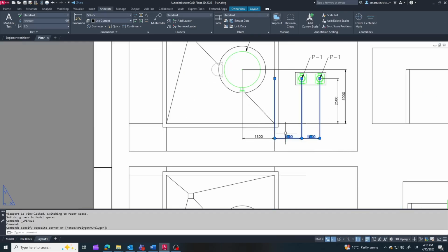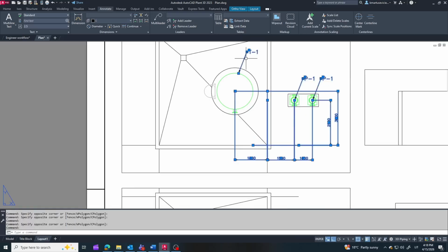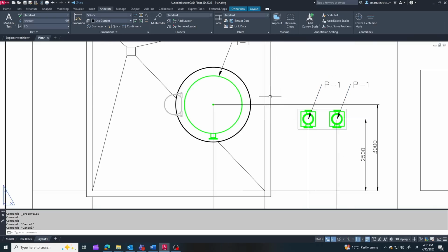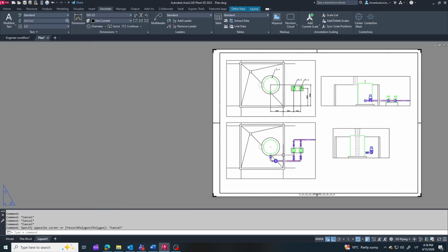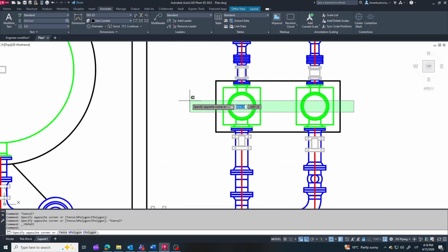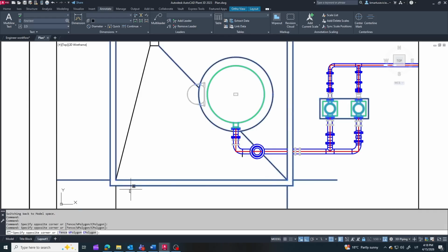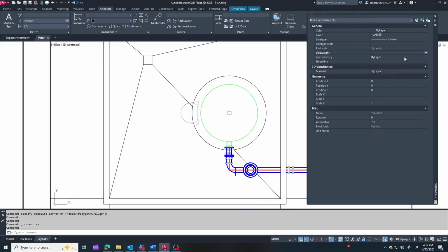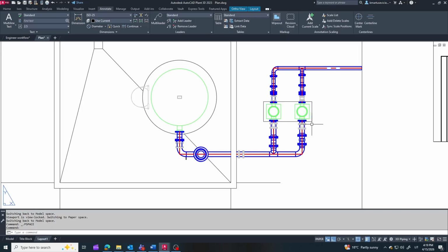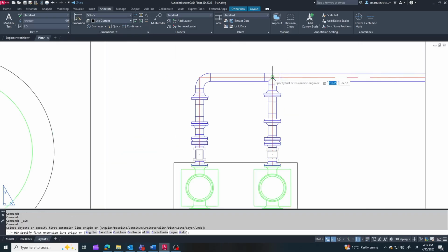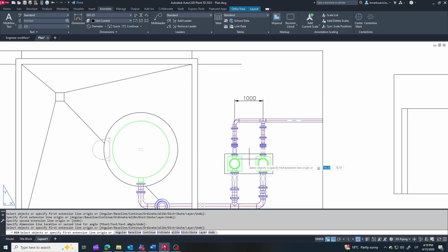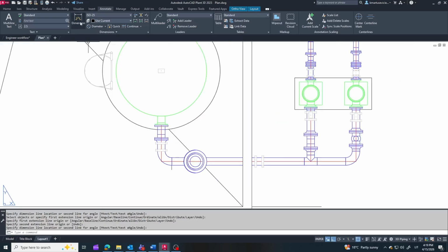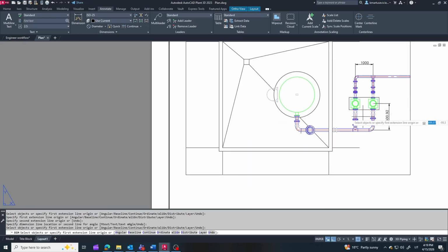Very often in larger projects, equipment changes over time, and sometimes you forget to update the task. For the civil engineers, like foundations for tanks or pumps, the result? The foundation is already built, but when the equipment arrives, it doesn't fit. In this view, the main focus is the piping, so I highlight the pipes and draw the other elements with thinner lines. The idea is not to overload the drawing with dimensions, but to measure everything that needs to be clear. Sometimes we mark certain dimensions with a star and add a note that these values should be verified on site during installation.